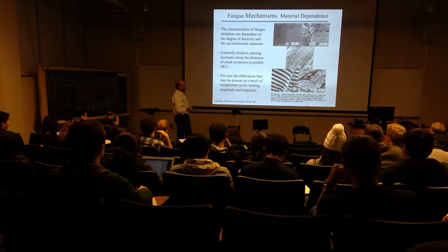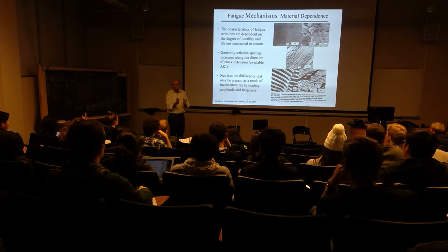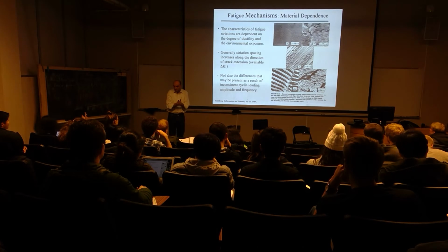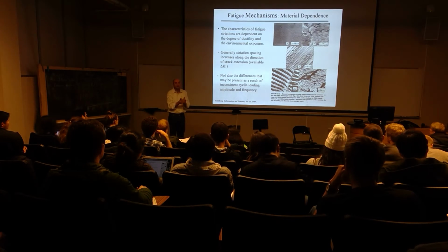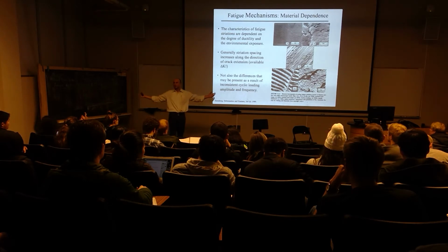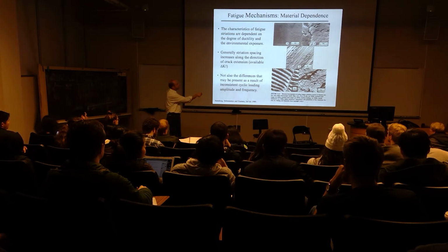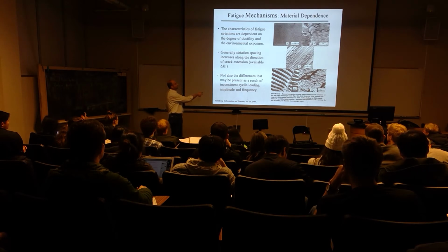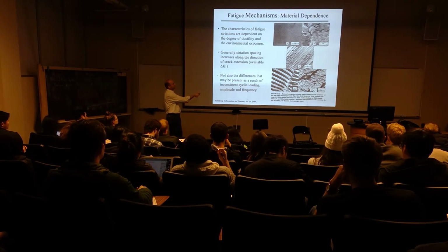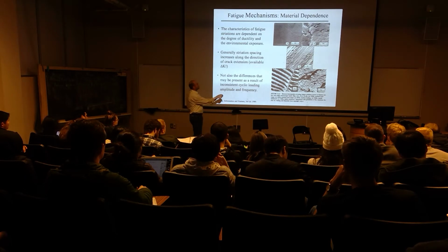Now, recognize that striations bow because of what we talked about, in terms of the interior of thick bodies being subjected to, most likely, a plane strain condition, more brittle. So actually the crack advances faster in that region than it does around the periphery because it's under plane stress. So anytime I see marks that have sort of a curvature, I know where the crack came from. That's one thing. So I would say, hey, the crack came from up there, and it went along that direction. B, it says SEM of a constant load range.